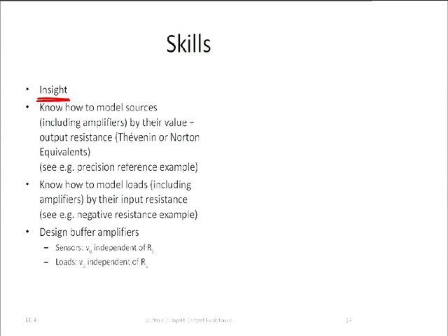And for example, a voltmeter, of course, does that. Voltmeter, very important. The input resistance has to be extremely large. So a reasonable model for a voltmeter is a really large resistor. And the DMM that we have in the lab, that resistor, you can look it up in the manual, happens to be 10 mega ohm. For some of them it's probably a little bit higher, and for others a little bit lower. Okay, so that's what this was about.